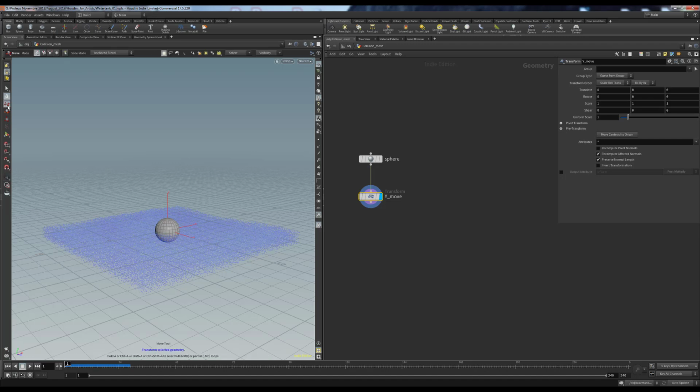You can move it using, for example, the handle, so you can move it in this way, you see, or you can just set the value here, or if you press the middle mouse button, you see that we have this scroll menu, and you can move here to move by 0.1. If you go here, you can move by 1. If you go here by 10. So you see it's really nice here. It is 0.1. So it is a really nice way to move stuff. Let's go to maybe 6. So it is 6 meters.